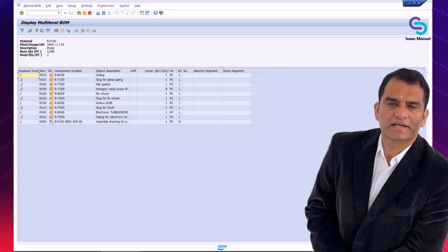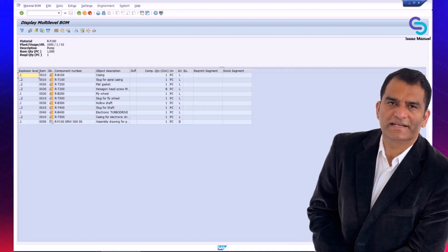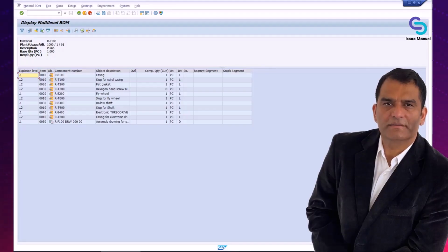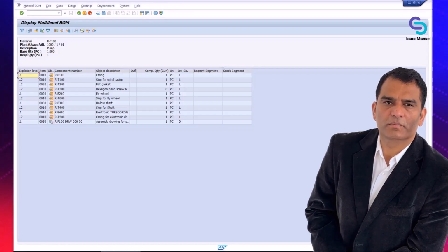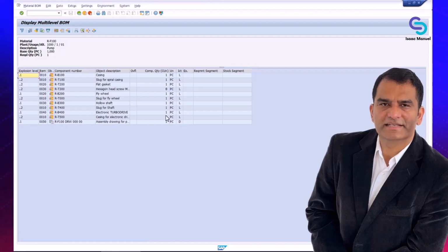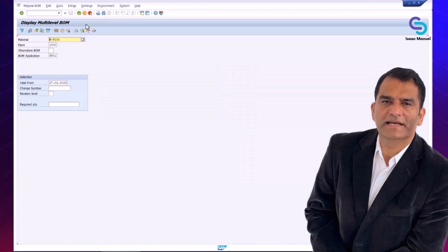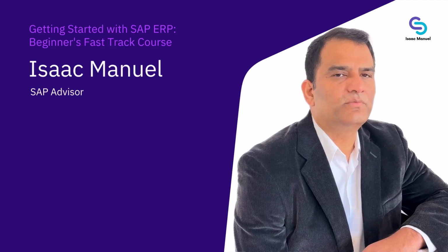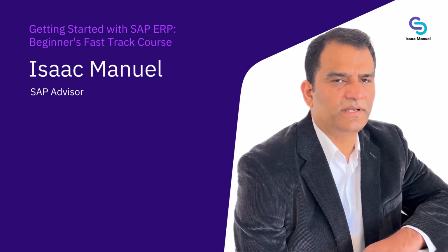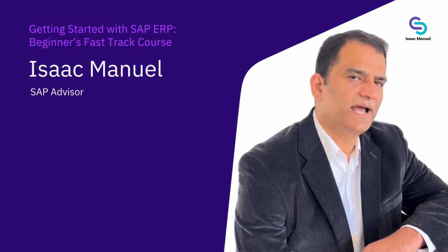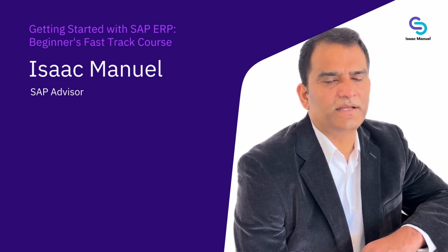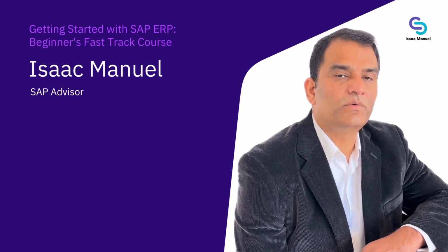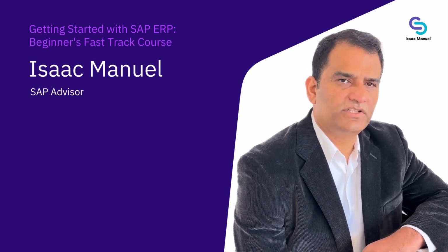Before closing, take a few moments to scroll through the entire list. Look at the quantities, component descriptions, and indentation levels to fully understand the relationship between parts. Once your review is complete, click the Exit button to return to the SAP Easy Access screen. Great job completing this walkthrough on the multi-level BOM report in SAP. You've learned how to access the CS12 transaction, input the right parameters, and generate a hierarchical view of all components that make up a finished product.